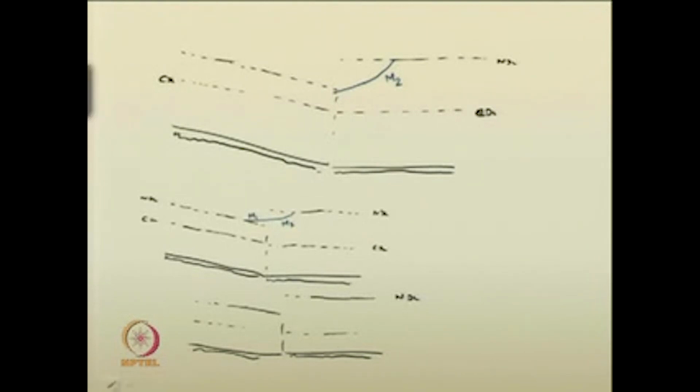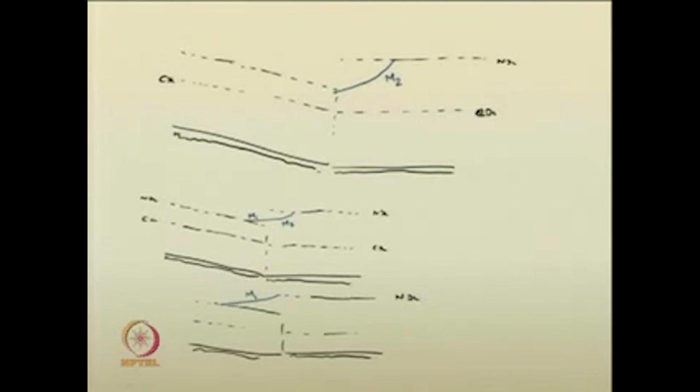The water surface will just start from here like this, and on reaching this junction itself, it will have a gradually varied flow M1 in channel 1 and reaches here, and in channel 2 the flow is entirely uniform, following the normal depth line. So, out of these three possible situations, which one do you think is correct, or which one is theoretically possible? Now, you look into these cases.